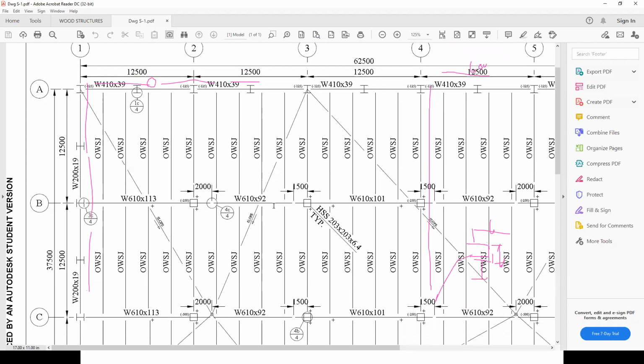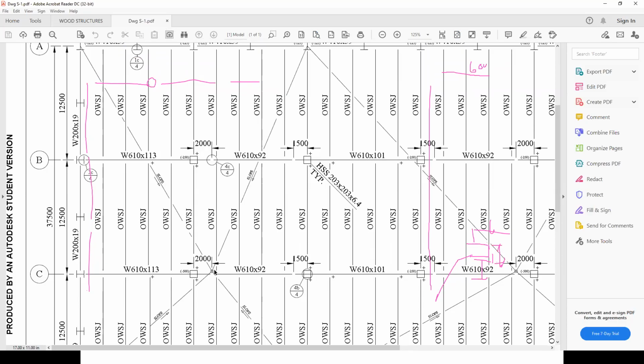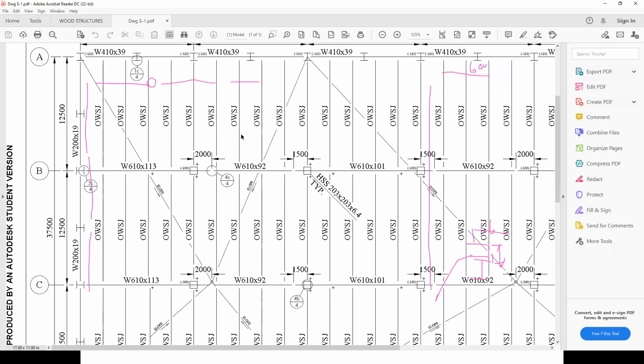Now, after that, what happens here is that they calculated the slope. In other words, they took the furthest distance from this drain here, okay? And then they calculated, for example, here they had 1250, 1250. And if I'm not mistaken, that would be 25 times 2, that would be 500. So what they did is they dropped the top of the steel right here to 500 millimeters below 6,000. In other words, that would be at 5,500. And then after that, this would be halfway between the two. So therefore, they would drop this by 250.